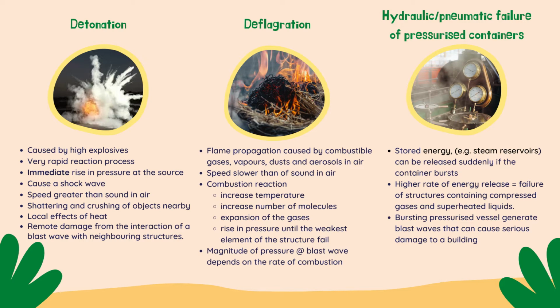Stored energy, for example in steam reservoirs, pressurized air containers, and chemical reactors containing a liquid under pressure, can be released suddenly if the container bursts. Higher rates of release of energy means that it is due to the failure of structures containing the compressed gas and superheated liquids. The bursting pressurized vessels generate blast waves that can cause serious damage to a building in which the vessel is located and to a neighboring structure. The majority of explosions in buildings result from a deflagration.